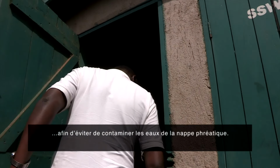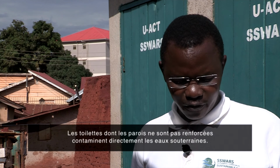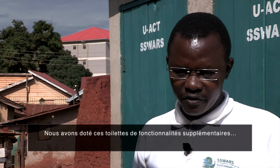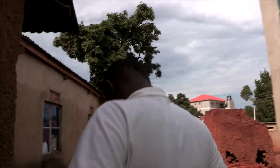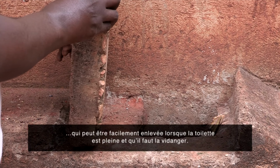It is lined so as to prevent groundwater pollution, because most of the low-income areas in Kampala are situated in areas with high water table, and therefore toilets which are not lined contaminate groundwater directly. We have given these toilets additional features to facilitate the emptying. For example, on the side, we have got an access point which is covered by a brick that can be easily removed whenever the toilet fills and needs to be emptied.